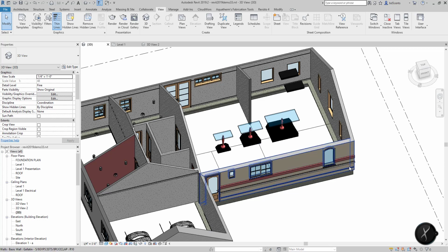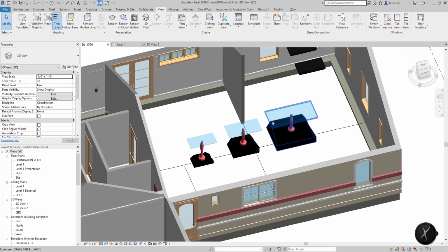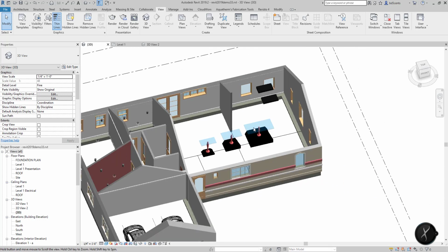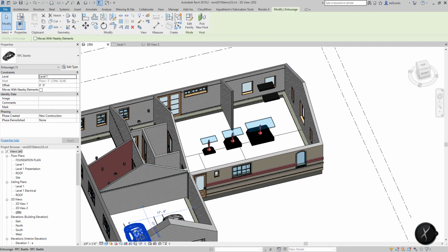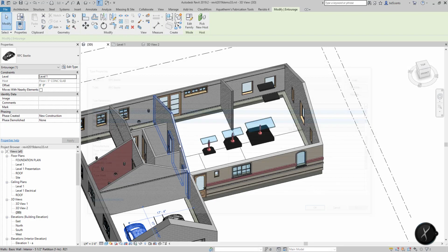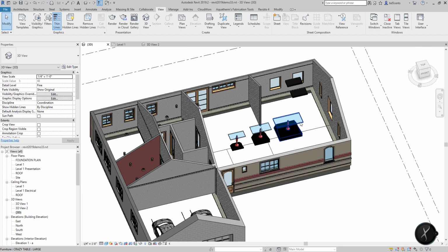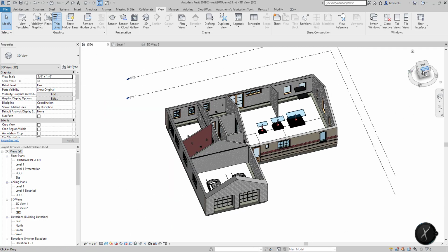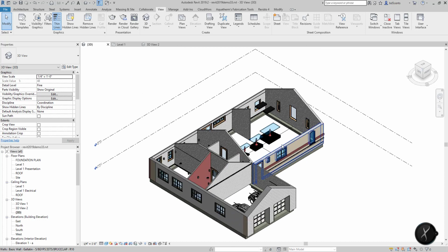That is the extent for this class of how families are going to function and what we're going to use them for, but begin to think about other values and other ways to associate these. If we look at these VW bugs, these are RPC beetles. They are families loaded in as entourage. Now, that's something that you could associate to be 3 different sizes of a vehicle per se, or 3 different sizes of a sofa. Families can become very complicated, but for the course and extent of this class for Revit 1, this will be the extent of those type-based parameters. If you have any questions, please email me or call me, and we can discuss what variables need to be changed to associate to these furniture families.